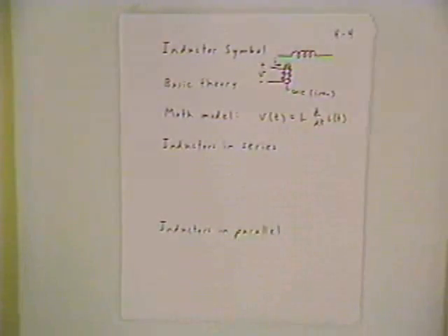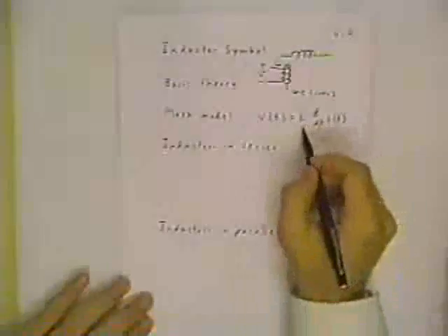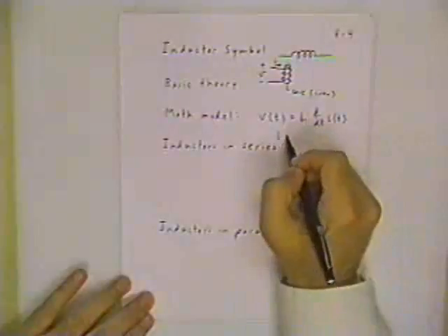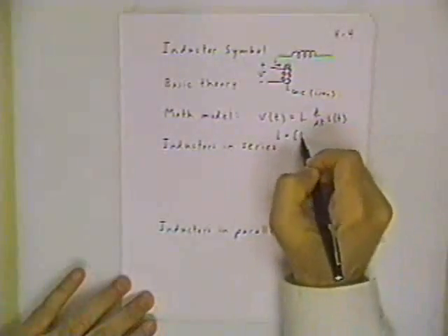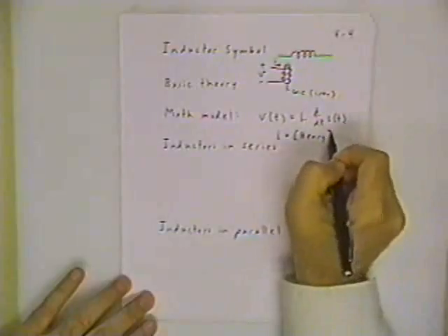Frankly, I find it much easier to understand and discuss capacitors with you. So the thing to do is understand the basic theory of the parallel plate capacitor to help you remember that linear model, that the capacitor current I is C dV/dt. And then once you've figured out and remembered the capacitor model, all you have to do is remember that the inductor is the companion component, then you just reverse the roles of V and I. You replace the capacitance with the inductance, and that's all there is to it. For an inductor, you have an element parameter called the inductance, L, in henries.